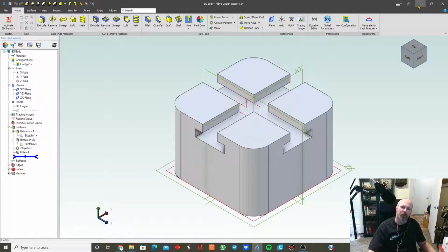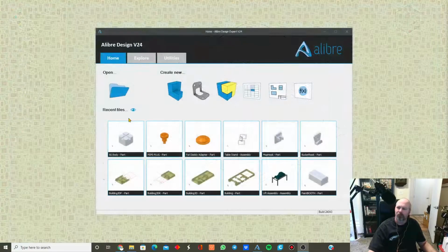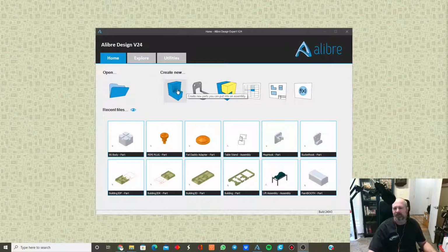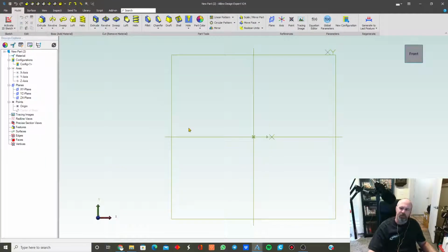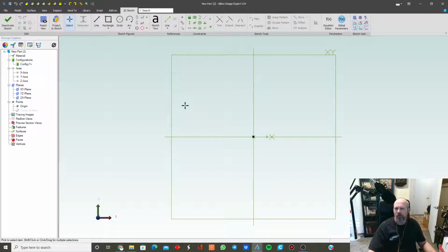Okay, so now we can close this out. We're going to make our slide next. Alright, so same basic thing as before. We'll activate our sketch plane, pick a plane that you want to activate, and again grab your tool and then draw out basically the mirror image, or not mirror image, the same drawing as that extrusion that you made before.